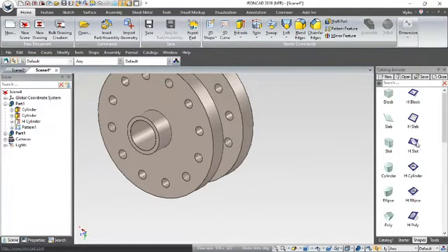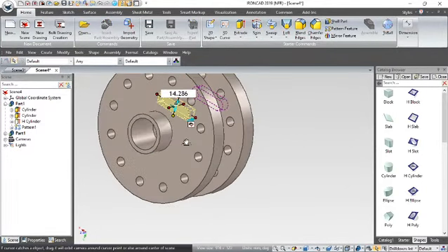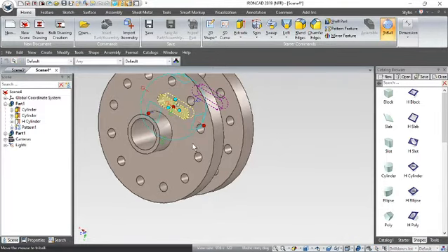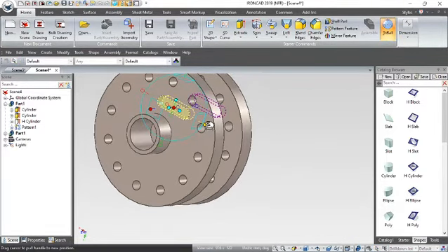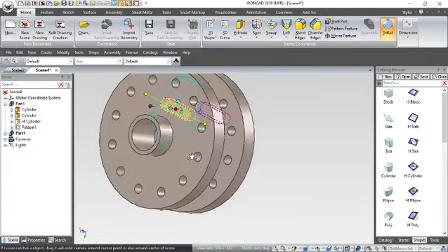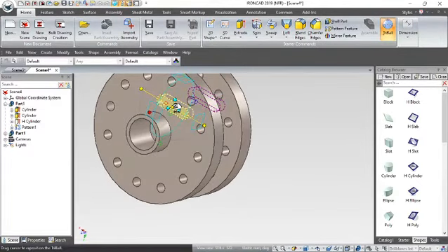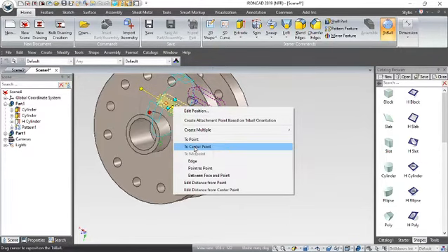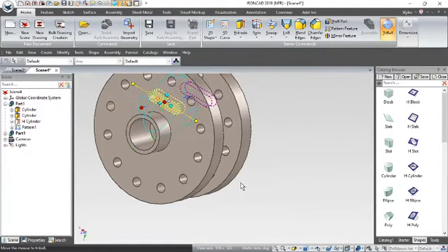So for instance, if I go to a hollow slot here, and I just drag and drop that somewhere in here like that, what I'll do is press F10 again to attach it to this slot. I'm going to pick on that outer axis with the left mouse button, signifying that's the direction I want to move it in. I'm going to hover over the center of the slot and say to center point, so that's now in the middle like so.